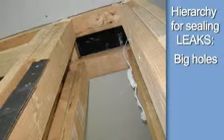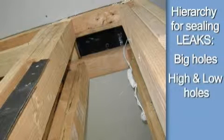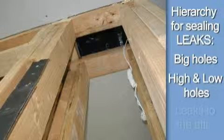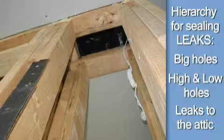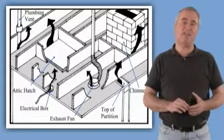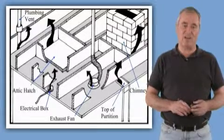We always want to seal holes located either high or low in the building, where the driving force pressures are higher. So big leaks, high and low leaks, and always leaks to the attic, since our attics are so hot in many climates.